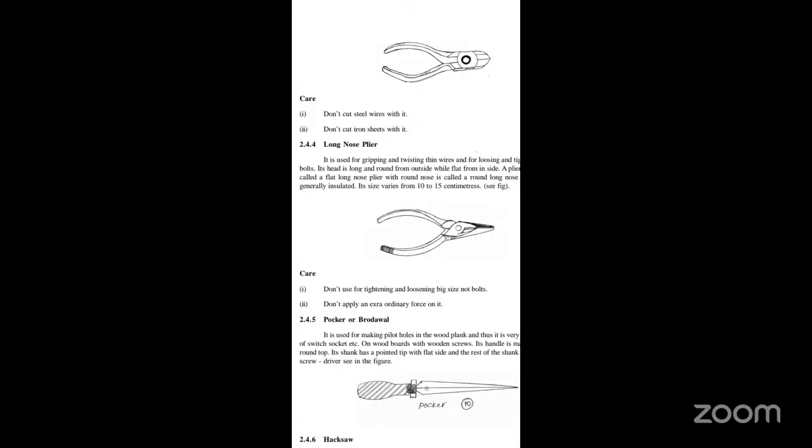What care is required for this instrument? Don't use it for tightening and loosening big size nut bolts. Don't apply extraordinary force on it.